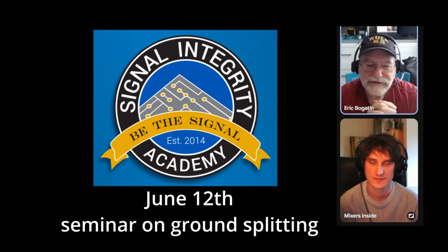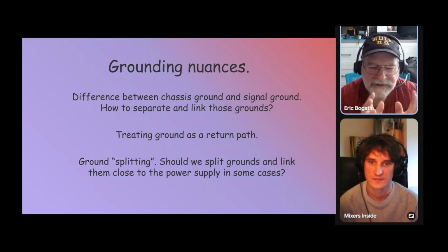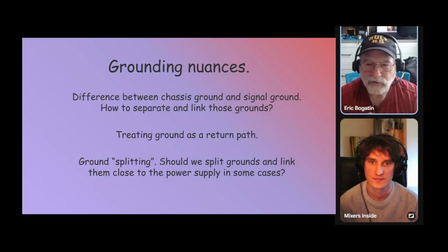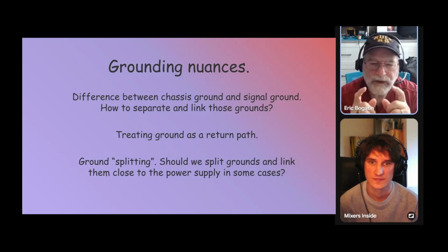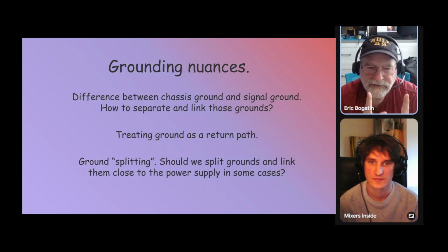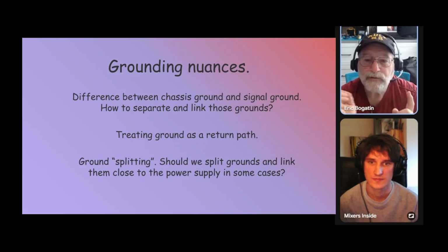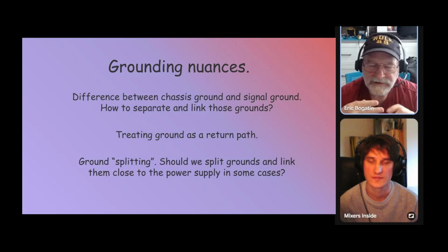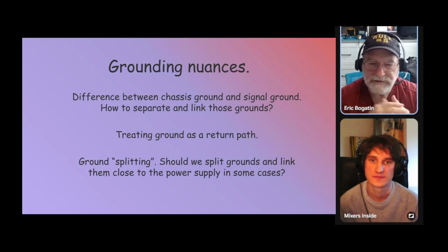The example that I show is generating this resistive IR crosstalk, when that conductor that we call circuit ground is also used for return current. So it's being used for two different, separate purposes.